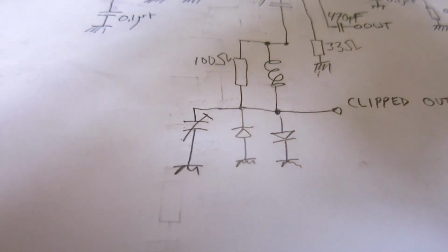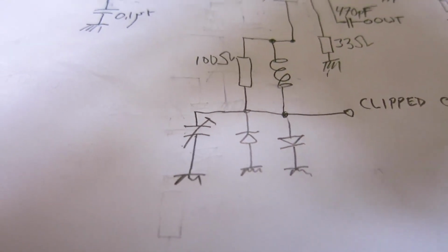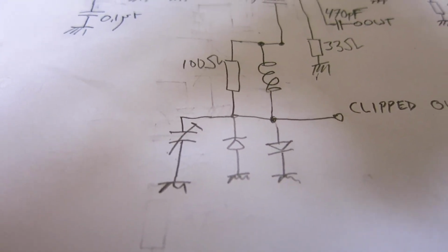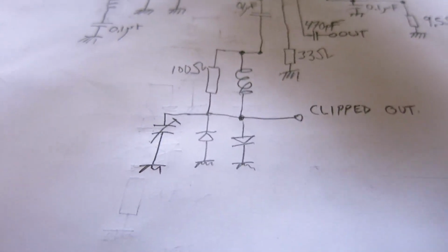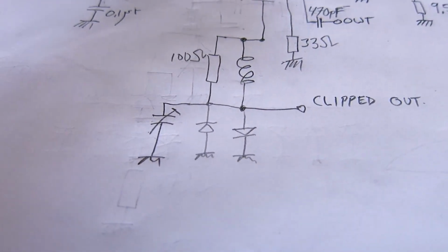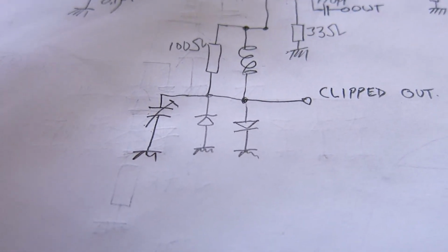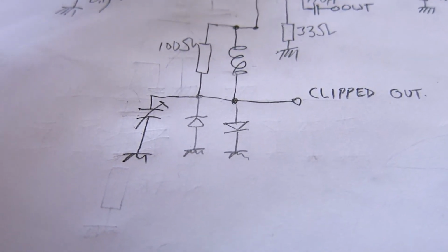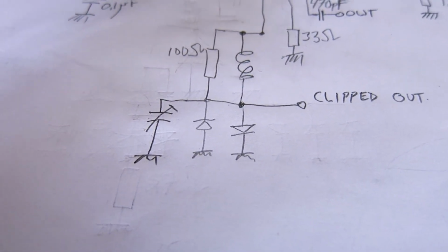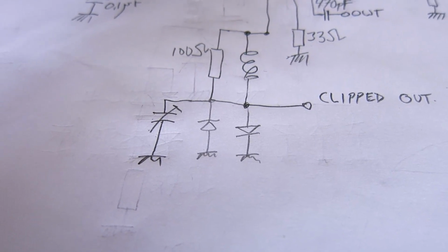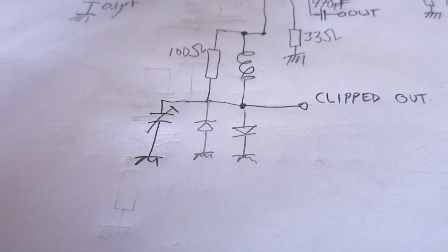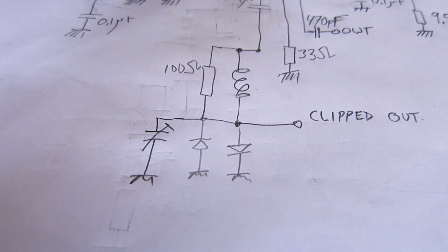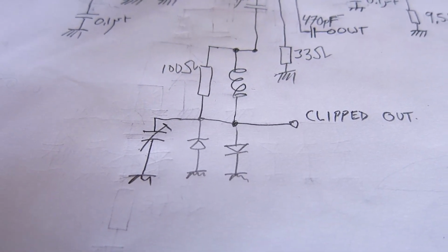I have reduced the number of diodes. Now there's just a single pair of 1N4148. This change caused the signal level to increase by about 1 decibel. So I have increased the input signal by 1 decibel to have the same signal level at input as I have on the output, to measure what will happen when I make an oscillator from this.